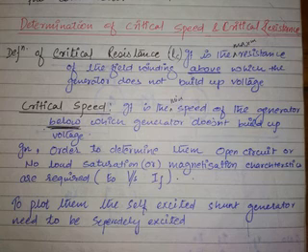Write down the definition for critical speed. Critical speed is the minimum speed of a generator below which voltage doesn't build up. Below which voltage doesn't build up. You underline "above" in the definition for critical resistance, and underline "below" here, just to make you understand the concept. While you plot a curve and calculate RC and NC, you just think about above and below these things.